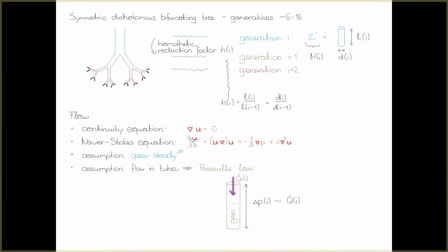Okay, and this pressure drop in Poiseuille's law is proportional to the mass flow rate. That also can be seen very clearly. The Poiseuille law gives us a parabolic profile, and when we integrate over that parabolic profile in this axisymmetric configuration, we have to get the volumetric flow rate. Multiplied with the density, we get the mass flow rate. That means when we increase the mass flow rate, we just have to rescale that profile by that factor.